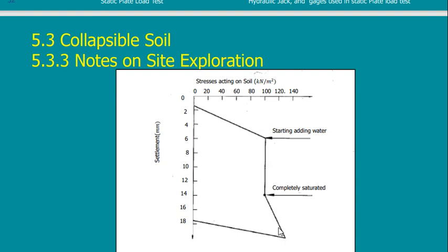Because here it was in the dry condition, and here it is in the wet condition, because I already have water now. So this soil was affected twice: at the beginning to have this sudden drop, and then later in its behavior, because the characteristics of the soil changed and the reaction to the load will differ from before.